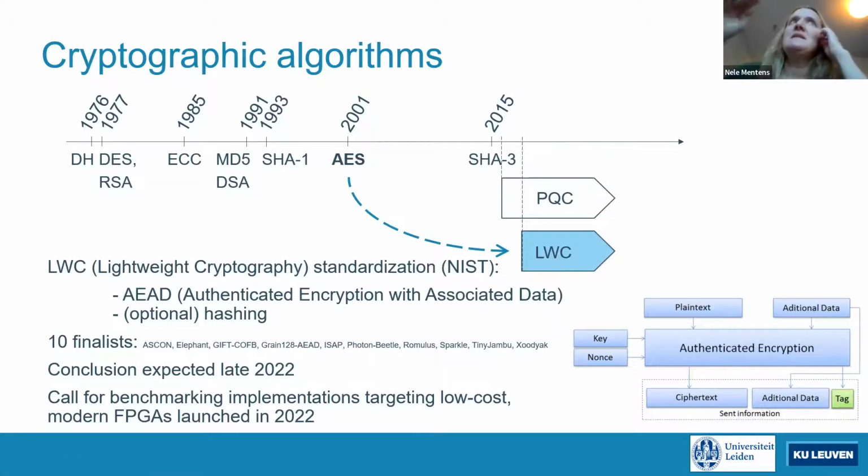The difference is, I must say, that in post-quantum crypto algorithms and traditional public key algorithms, it really makes sense to use the FPGA also as an end product, because the advantage of using FPGAs is clear: you need these parallel computing capabilities. In this case, the target is really lightweight crypto. And of course, it's also for embedded software platforms, but when we go to hardware with these algorithms, then I would say that the main target would be very low-cost and low-energy ASIC implementations.